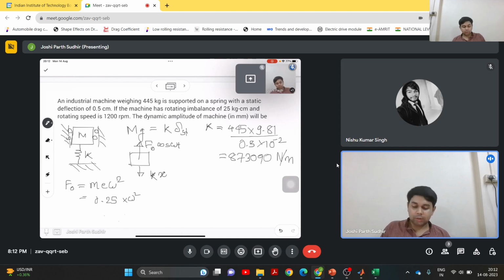So what is the excitation frequency over here? Omega. So omega will be 2 pi by 60 into 1200.